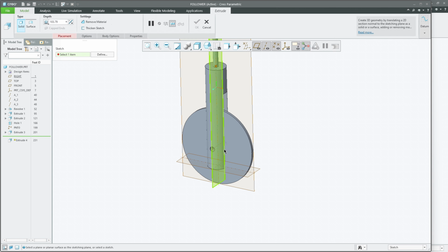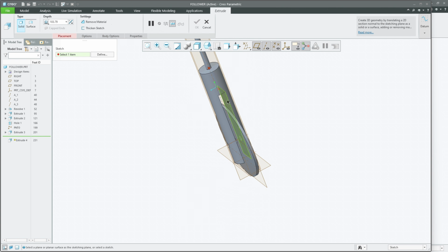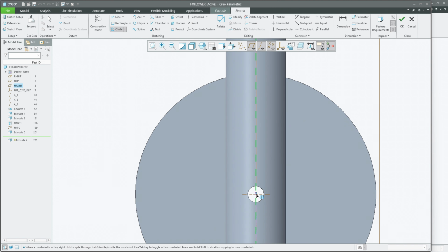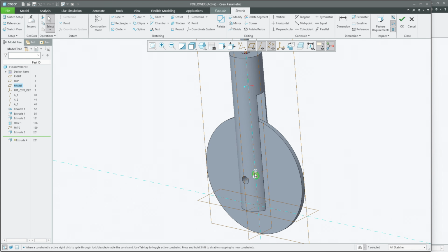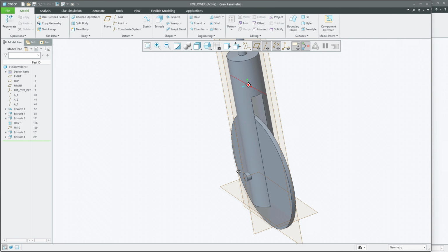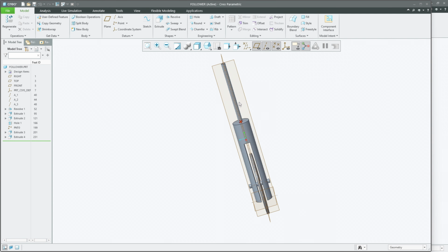So next I'm going to have a pin design here. For that I'm going to select the extrude command in the front plane, select the circle, and draw a circle here, the same as it is. Click OK here, and I'm going to make this symmetric with a length of 60 or 55. 50 is fine. Yeah. So now you can see this is going to be a kind of plunger,